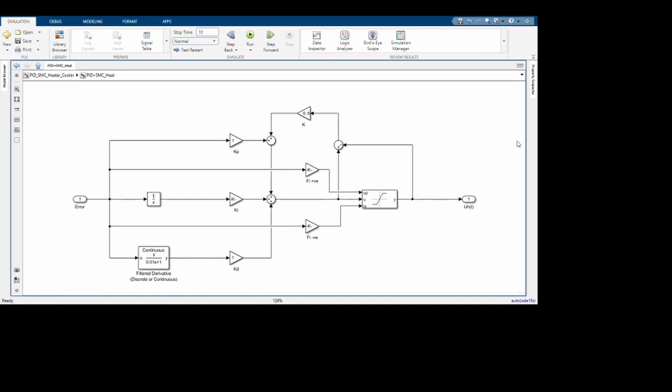A lot of PID controllers are simple to implement, but they overshoot very easily. By overshoot, I mean they will go beyond our set temperature value, and that could damage certain components. And even if you have properly tuned your PID controller, environmental changes and device property changes will never accurately give you 100% good results.